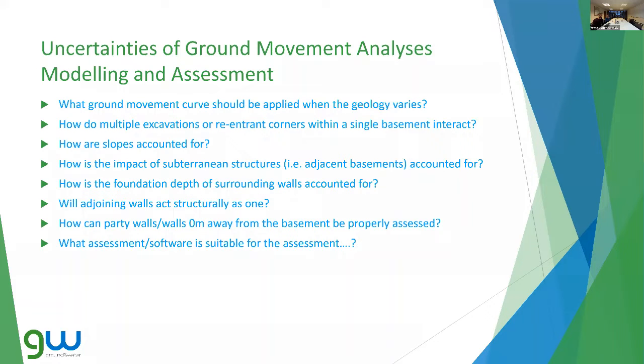what ground movement curve should you apply if the geology varies? Obviously, if you're in sands and then stiff clays, which could be the case in some of these places in London where it's gravels over clays, or you may have softer firm clays like head deposits over much stiffer London clay, what ground movement curve should you apply? Should you apply a softer firm curve and be over conservative, or should you apply a stiff clay curve and be maybe not conservative enough? It's a balancing act, and a lot of engineering judgment comes into it.